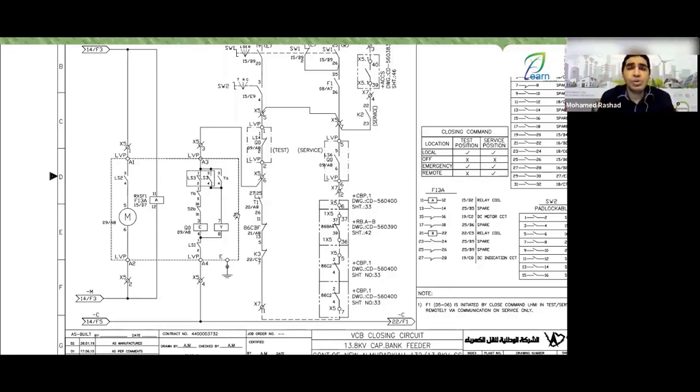Great. Now, all this drawing is implemented where? It's implemented in the upper part of the switchgear, correct? Great. Okay. Anything outside this upper area, in the low voltage compartment, must be drawn with a dotted square around it. If it's a dotted square, like you see here, it means it's something located inside your cell.